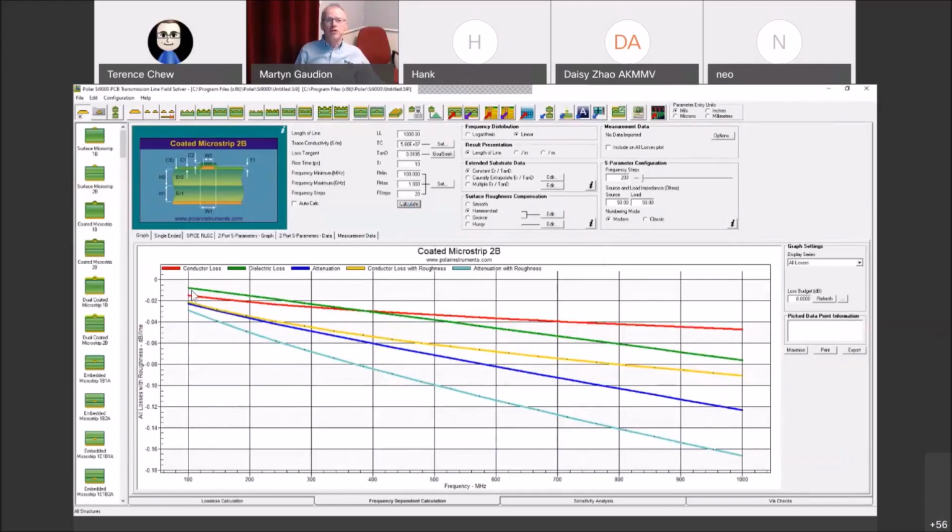Okay, so you can see that at very low frequencies here, the dielectric loss is quite low and the conductor loss is higher. And then as the frequency increases, the dielectric loss overtakes it and becomes the main factor of loss. But here what we're doing is breaking down the total loss. And in this case, in this 1 inch, we've got 0.16 dBs per line length.